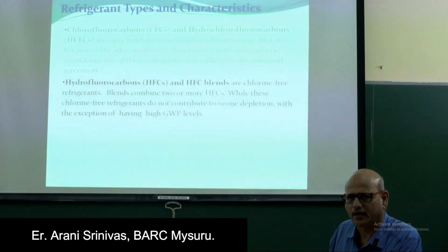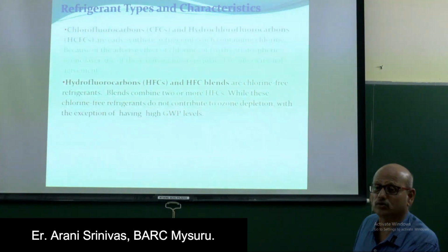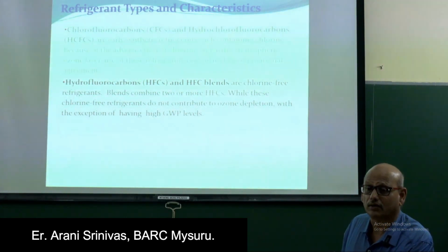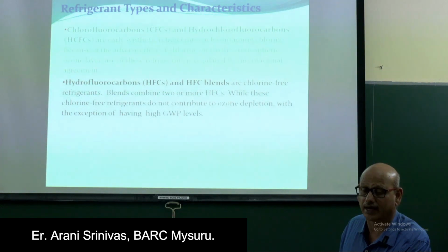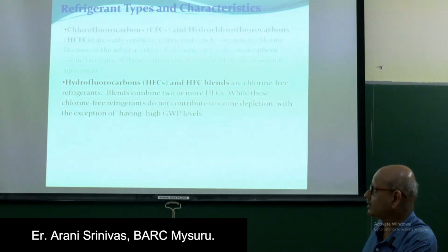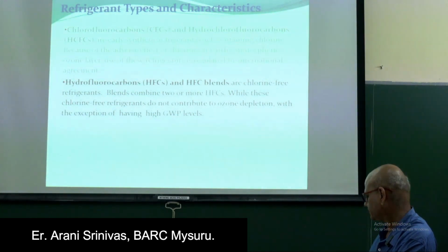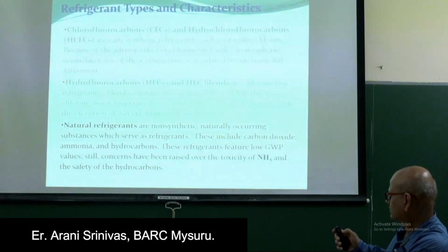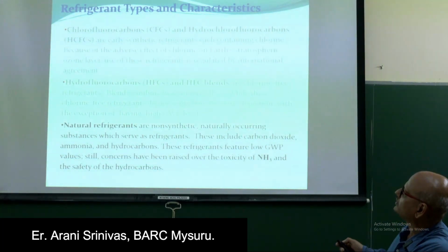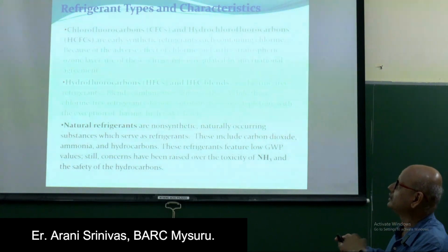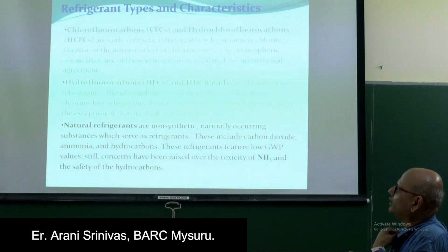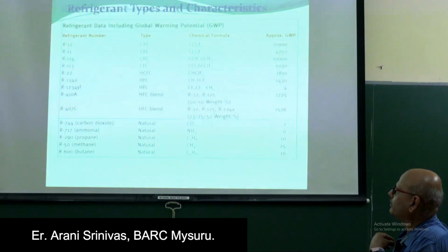CO2 is considered the reference, and with CO2 these global warming gases are compared. HFC gases have 1500 to 2500 times more than carbon dioxide. So HFC gases also create a problem for global warming. CFCs, HCFCs and HFCs are synthetic. HCFCs are early synthetic refrigerants, each containing chlorine, because of the adverse effect, again I am saying.